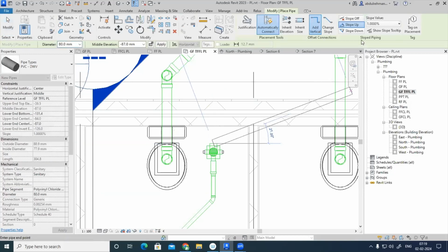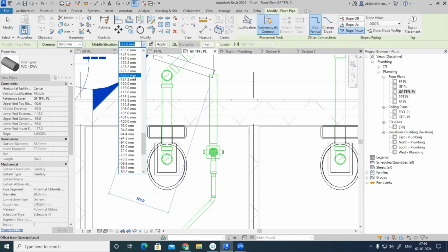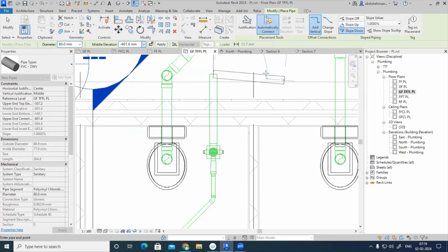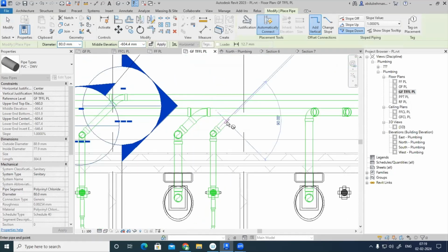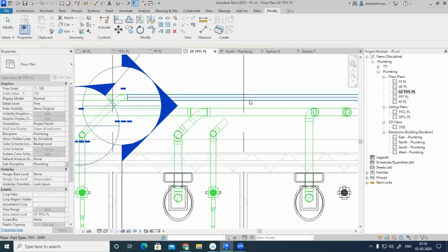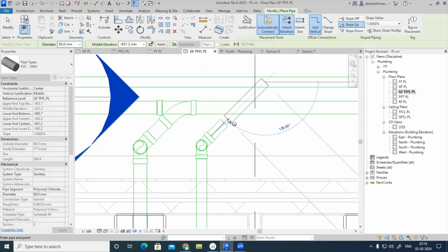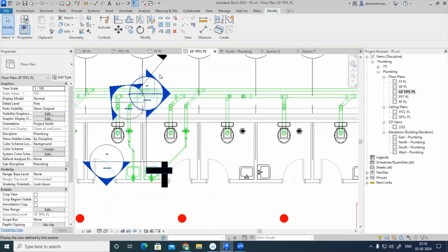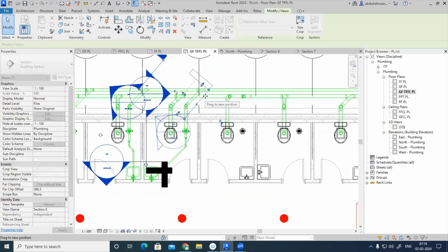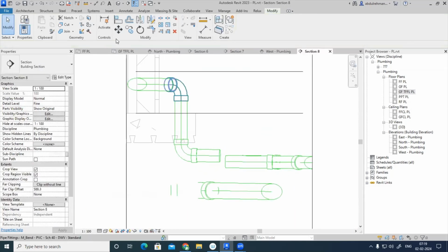So 80 mm outlet, that is slope down only, we'll be taking the pipe outside, and you can take it down, let's say like this, keep it there 45 degree. Now just select this pipe, create similar, inherit elevation, slope upside. Okay, make it like this. Now you can go to the sectional view of this. Align both the pipe, this one, trim and extend, join it.